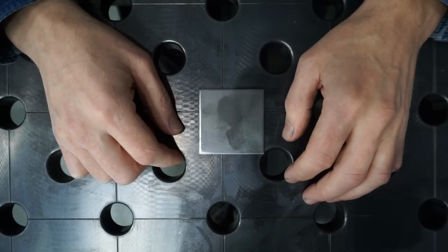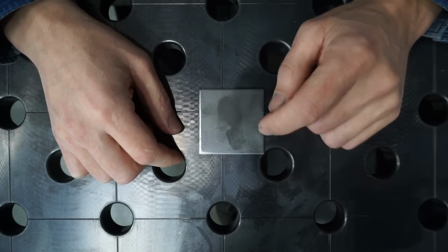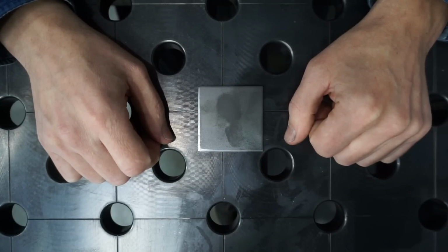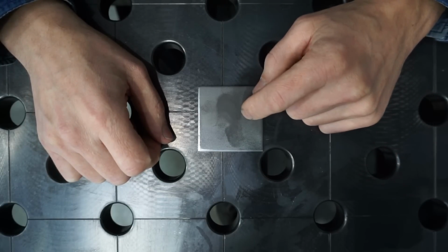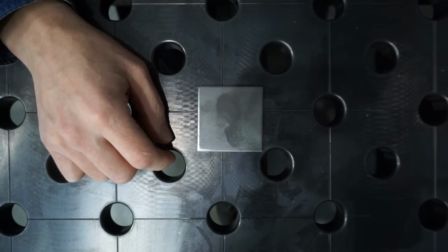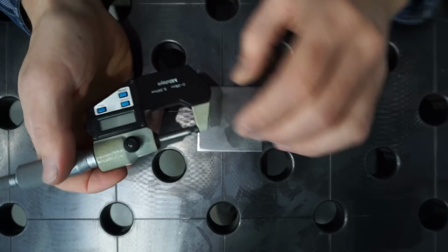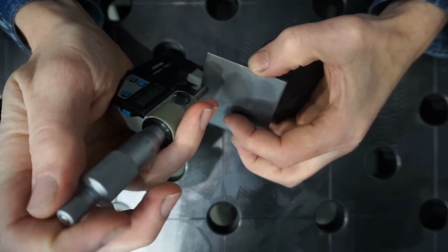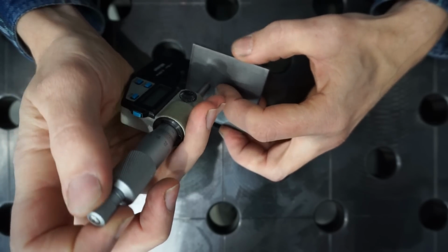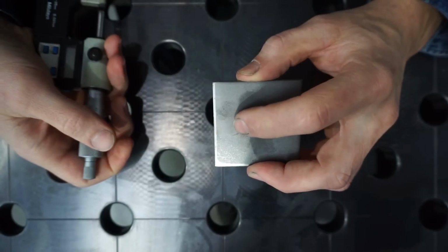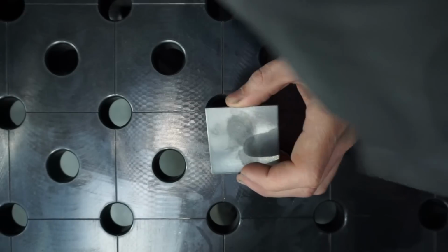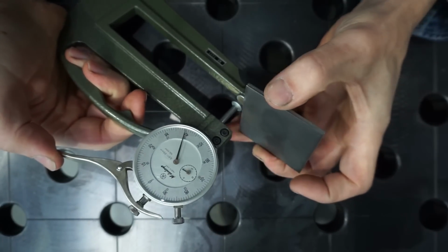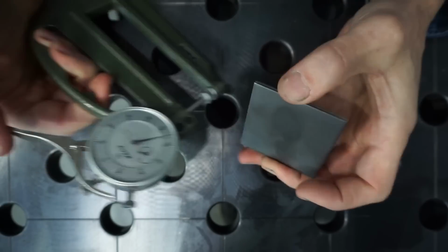Let us begin with studying the effects of the single heated spot on this piece of 3 mm mild steel sheet metal. First, we want to place a heated spot somewhere on the inside of the sheet where we can measure the thickness with the micrometer. If you want to do this experiment for yourself and have a micrometer like this, keep in mind that the throat depth is limited. So in this case we could place a heated spot approximately here. But for the experiment at hand, I will be using this thickness gauge here, which allows us to take a spot right in the center.